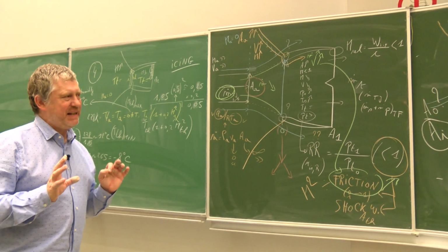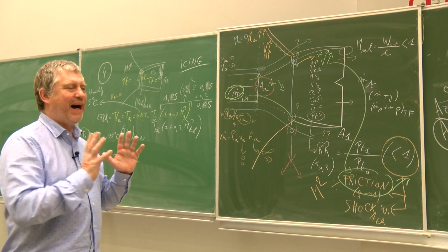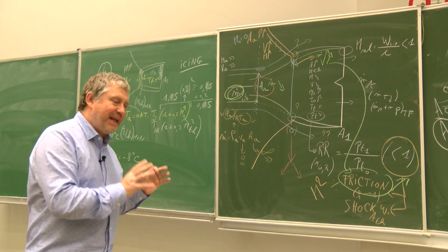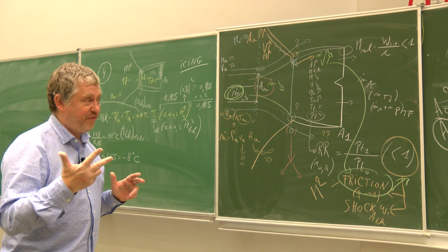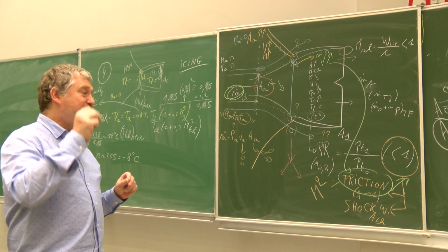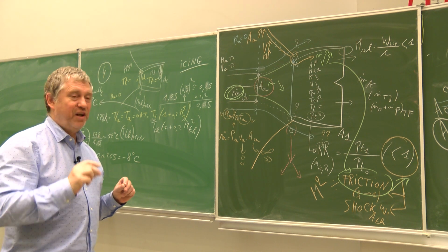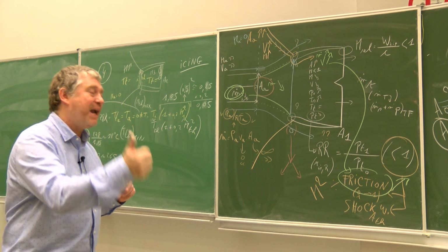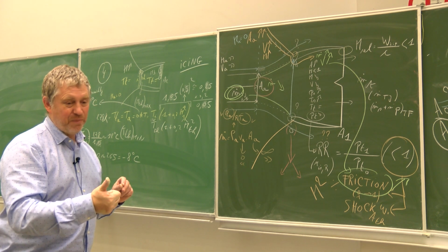And we have already discussed that a lot. We discussed it related to hot, high and humid, the combination of three very bad conditions. You combine even worse conditions due to the high mass flow rate, which means the ram recovery will be lower.